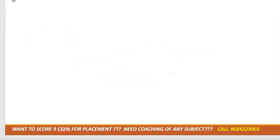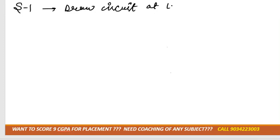So you can write down step number 1: we need to draw the circuit at t equal to 0-, then we need to calculate Vc(0-). This is particular for the RC circuit.